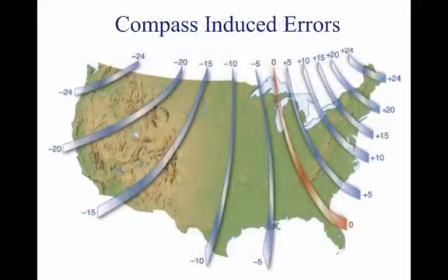The magnetic compass is the simplest instrument in the panel, but it is subject to a number of errors that must be considered. The Earth rotates about its geographic axis. Maps and charts are drawn using meridians of longitude that pass through the geographic poles. Directions measured from the geographic poles are called true directions. The magnetic North Pole, to which the magnetic compass points, is not co-located with the geographic North Pole, but is some 1,300 miles away. Directions measured from the magnetic poles are called magnetic directions.